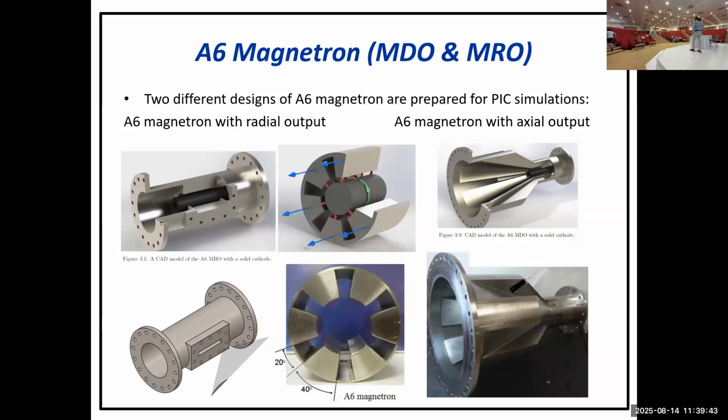But in the 70s, I think, they came up with pulse power. Just to let you know, conventional devices that can generate kilowatts of power use power supplies and modulators to drive them. Those can go to high voltage, but the currents are not in the range of kiloamps. A pulse power system like a Marx generator can produce currents of kiloamps, and that allows you to generate a gigawatt of power, but at very short pulses.